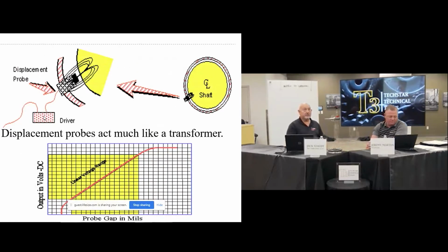We look at a displacement transducer. It's actually measuring, using eddy current, the linear motion of the shaft. So for this system to work properly, you've got to have everything perfect. And that's a good point. When we say the shaft, typically these systems come off the shelf calibrated for 4140 steel. If your shaft has a chrome coating, or you're looking at tungsten carbide, or a different shaft material, you need to make sure you specify that on the front end of putting one of these systems in.